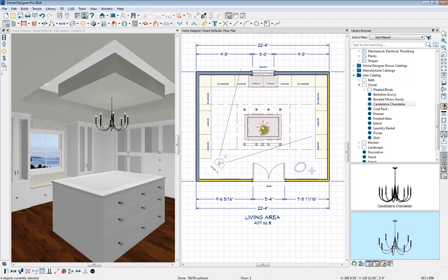And let's add in some more lighting. So we're going to do just like we did with our soffit. So we're going to do a copy and paste in place. And now that we have another copy, we can move those out. Let's rotate those lights around. And I'll move them up. And I'm also going to reflect them. So we'll make another copy here. Reflect. And now with a couple quick clicks, we have our lights placed.